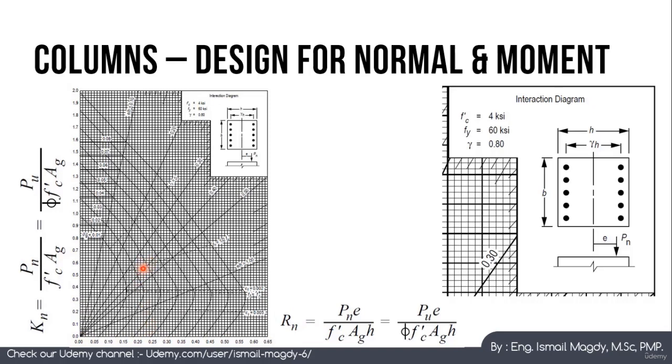Whatever point you choose here, you have these lateral curves. Each one has a percentage of reinforcement, starting from, as you can see, 1%, 2%, 3%. It keeps going up till 8%, which is the maximum reinforcement for a column. Wherever your point lands after you go vertically and horizontally, this will be the reinforcement percentage required for your column. So let's have an example of this.